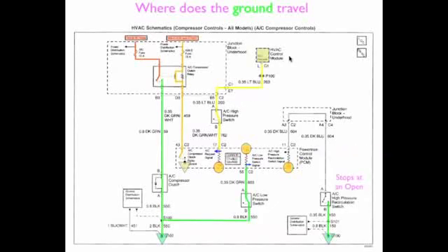Now how do we know that this HVAC module sent ground? It doesn't say it up here, but if you know the diagram and how it works, the diagram shows that we've got 12 volts. 12 volts needs ground. This switch is closed, so the ground has to be coming from here. If this were to send power, you'd have power meeting power, and that wouldn't work. You have to have power here and a ground here, and then you'll get your signal. So let's see now how this PCM handles all this and what it actually does.